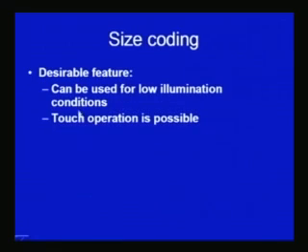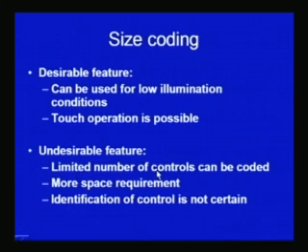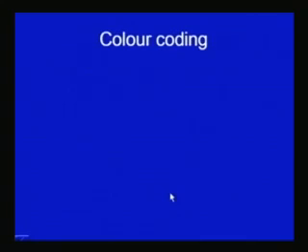The size coding also has desirable features like use under low illumination conditions, and touch operation is possible, and a limited number of controls can be coded by this method. More space is required in size coding for coding the controls, and identification of the control is also not certain in size coding, especially when gloves are used.